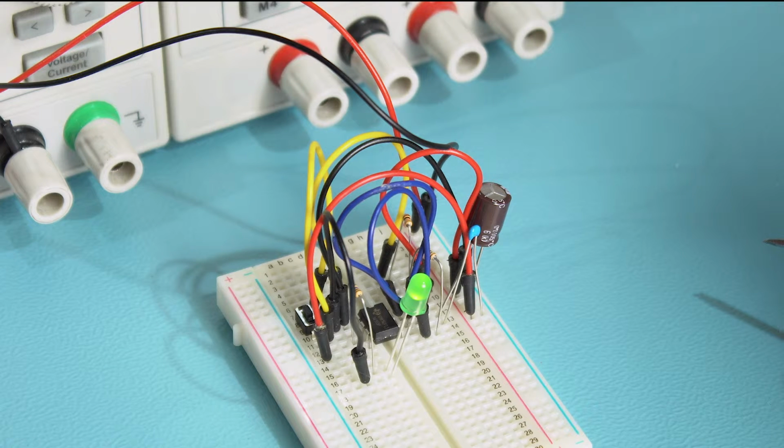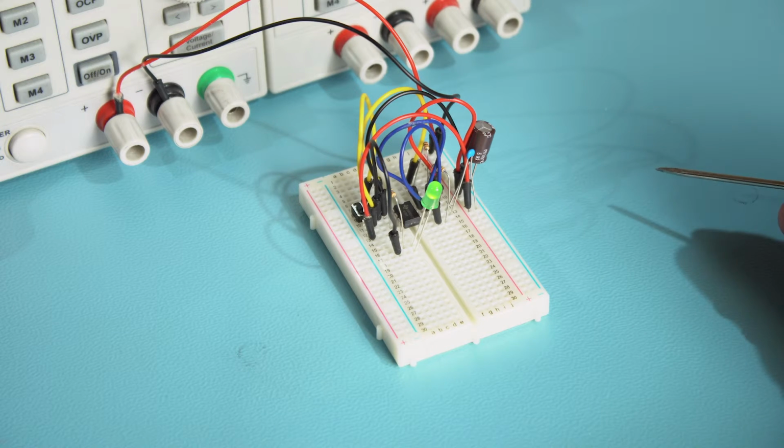Sometimes the system generates very short, sometimes multiple impulses, and our task is to do the work once. Then we can tune such a multivibrator to a bit longer time than the duration of this series of pulses, and we can use this information as one event.